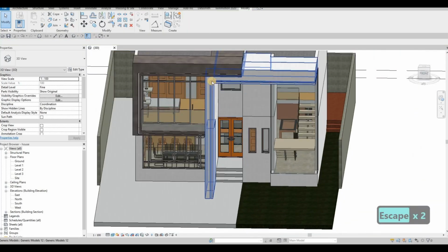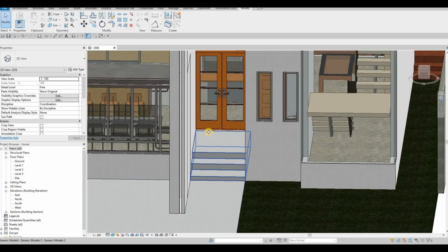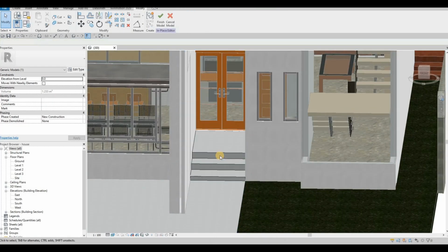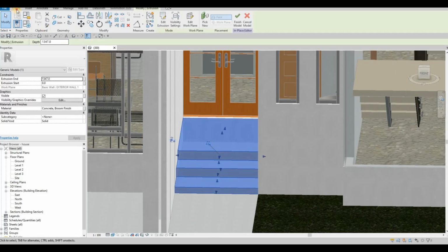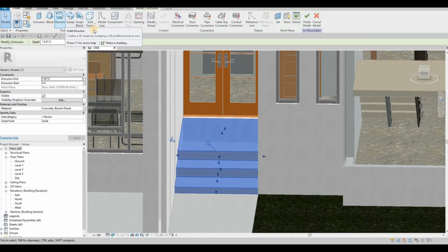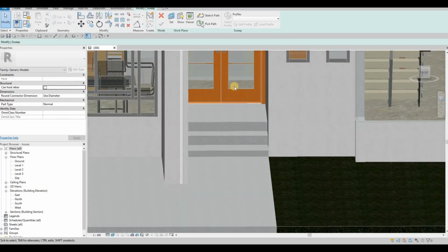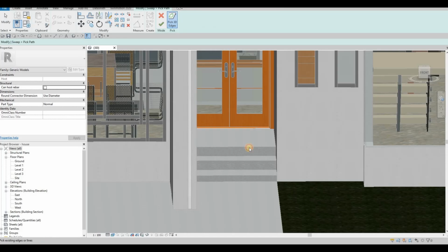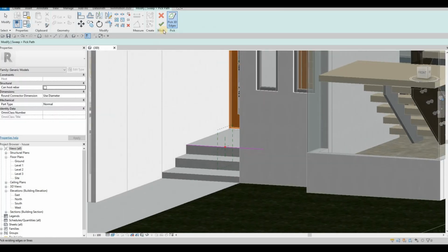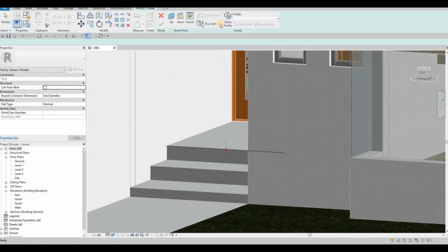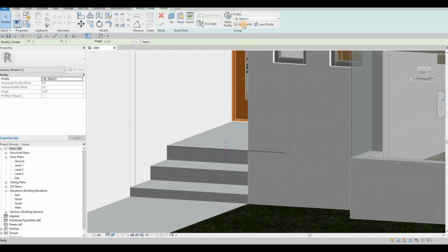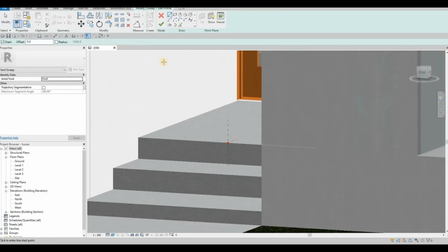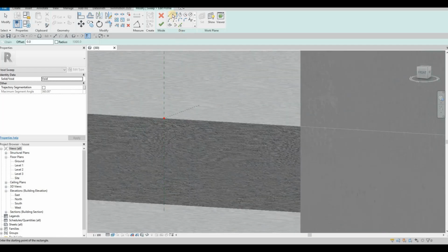So we're going to create the lighting that we have on this model. I'm going to select that, edit in place, and then we can create the void form and then void extrusion or sweep. So pick a path and we're going to select this one, click finish, and then go right here and edit profile again. And then from here we can create our void extrusion.